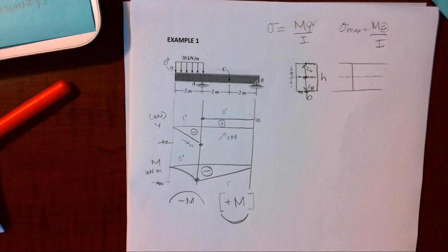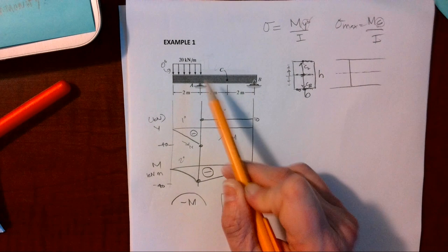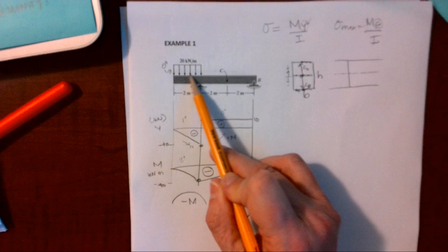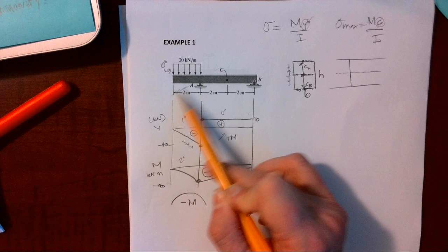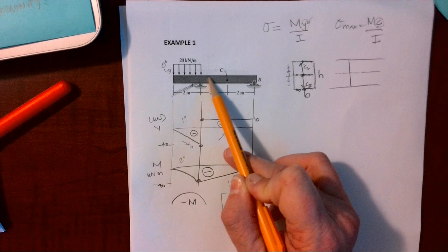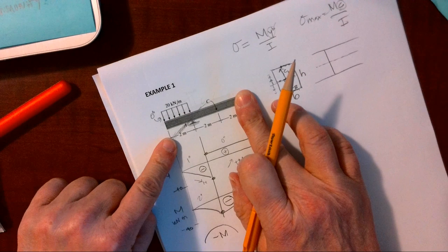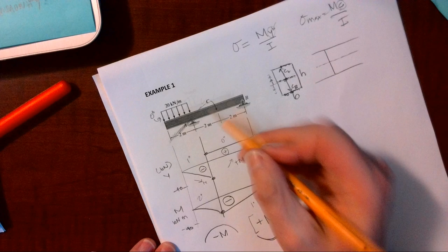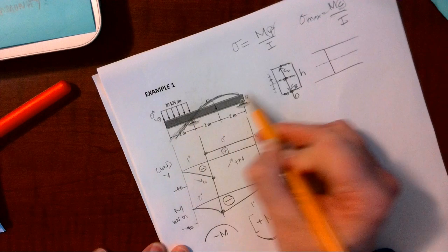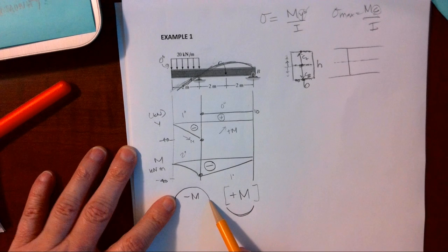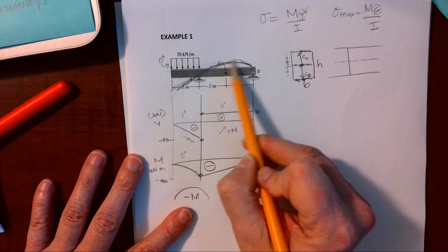So if I looked at this beam, I am connected at A and I'm connected at B, and I'm loading this like a bunch of us standing on the end of a diving board. So this is going to want to go down, okay? And as it's going down, if it were just a teeter-totter, it would look like this. But it's not a teeter-totter because we're connected at B. So it's going to want to kind of do something like that, okay? And I can see that curvature is indeed like an unhappy face or a rainbow. So for negative moment, we can see the behavior, it's very exaggerated, is negative.